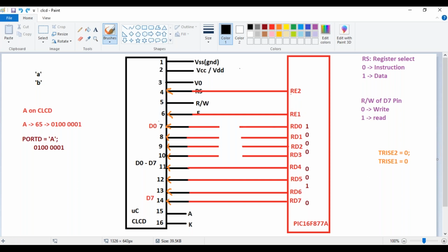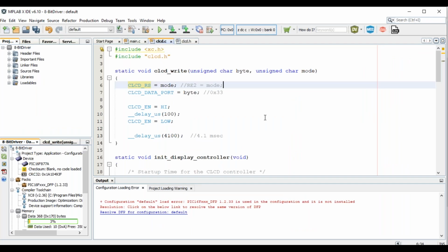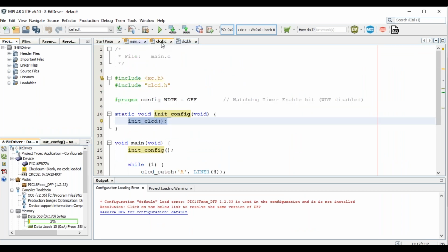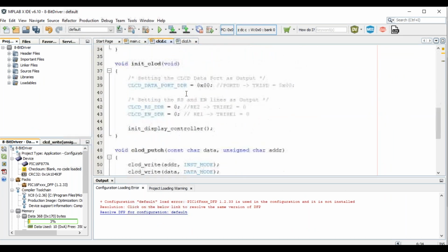I did not write to RE2 and RE1. Can you observe? This is the reason why I write what it is representing every time. Please see the initialization. Did I write to RE2 and RE1? I wrote it to the... See, this literally says you people are not paying attention to the basics. If you have to set the direction, I will never use RE2 or RE1. The direction, whether it is input or output, will only be specified with the help of the TRIS register.